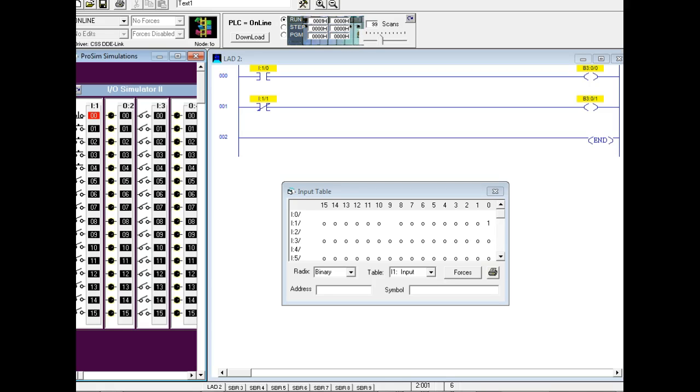But it's examined, and it's saying it's true if it's what? Yeah, it's examined and open. Is it? So is it what? It's still true. Well, by George, it's true. So that's why, and it's a normally closed contact, and it's true. Okay, so the examine open and examine closed is referring to the switch. We don't care about the contact. Is that what I'm understanding? It's determining what it's getting back from the input.